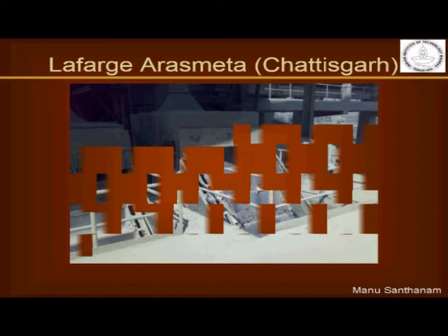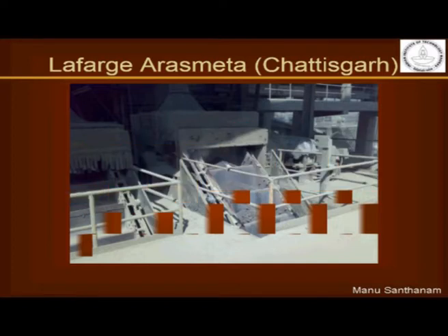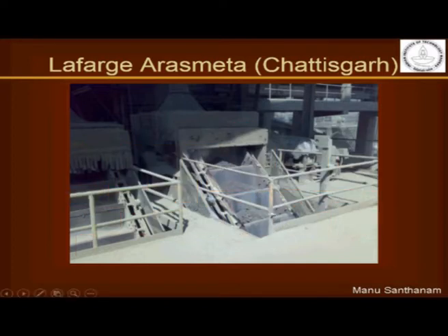And so this is the clinker that is actually coming out of the cooling process. You can see here the clinker which is coming out of the cooling process. This clinker is almost looking like nodules. So it doesn't look like a powder. This is because of all the fusion that has taken place inside the rotary kiln and after the cooling process. So you can actually see the clinkers in the form of nodules. You can imagine that this has to be broken down into a very fine powder to get the typical cement that we are all understanding, or what we typically get in the market.